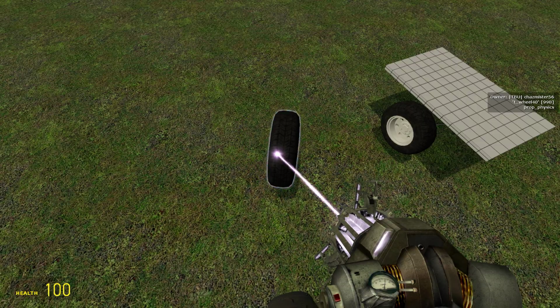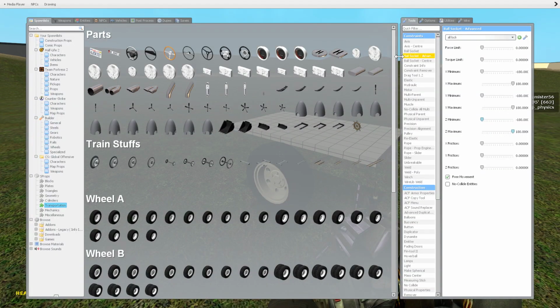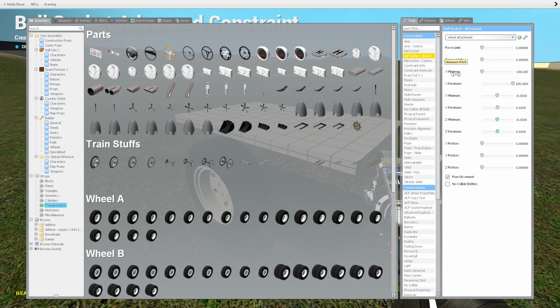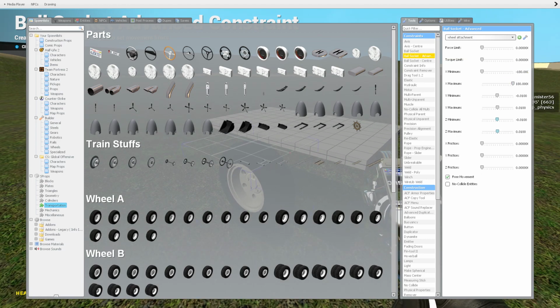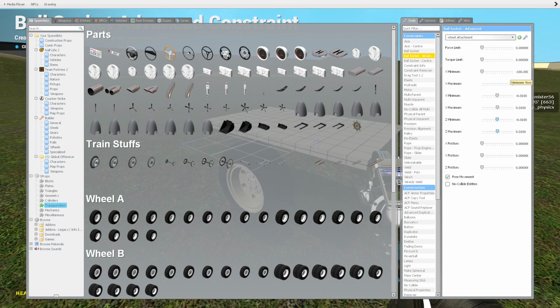This is Z. And since we're not mounting this to anything here, we're just going to use a very simple wheel attachment ball socket, which is negative 180 on the X minimum and maximum 180 on the maximum. And the rest of these are locked, and you do not want to set these to 0 because it will break the ball socket and it will not be very stable. So the best one to use is 0.01. That is very strong. So basically you set your Y and your Z, the locked number, and you don't have to worry about friction on any of those.